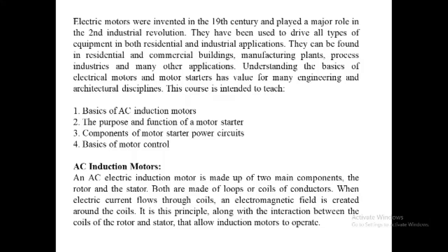The actual speed of the motor will be slightly slower than the synchronous speed of the electromagnetic field, and this difference between the synchronous speed and the actual speed is called the slip. The slip for most common design motors is 3 to 5% of the synchronous speed.